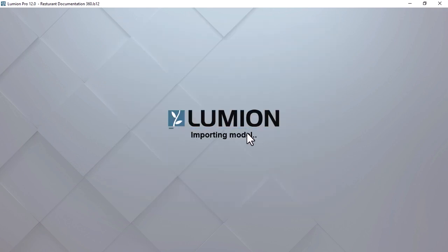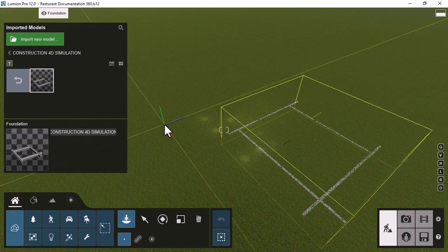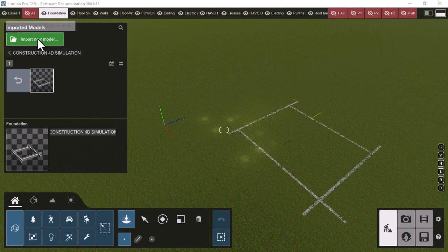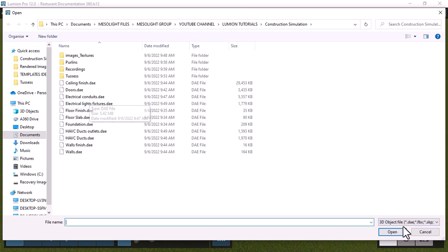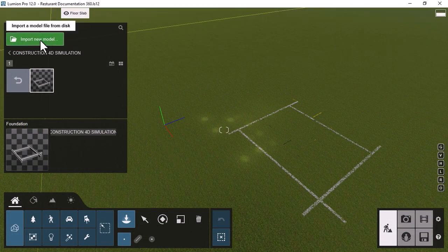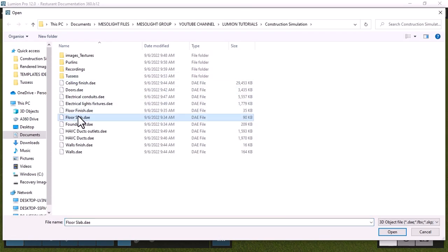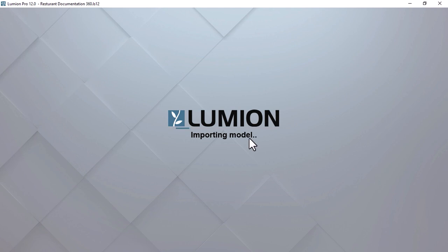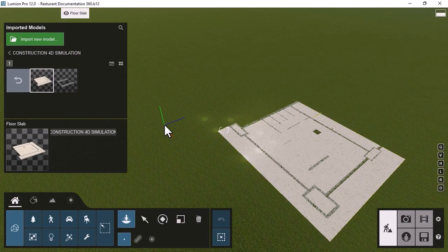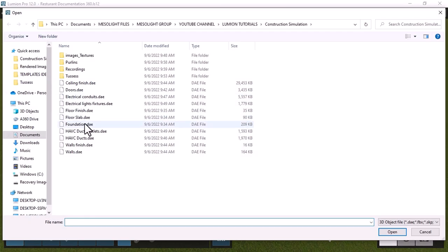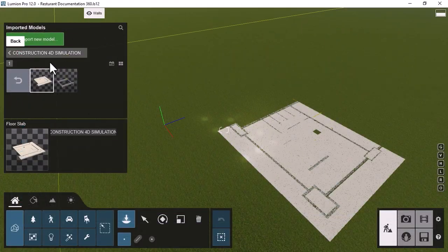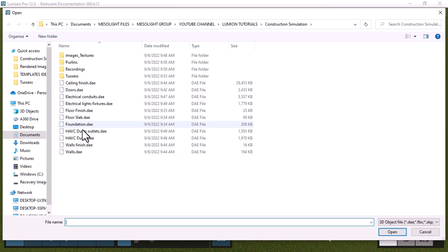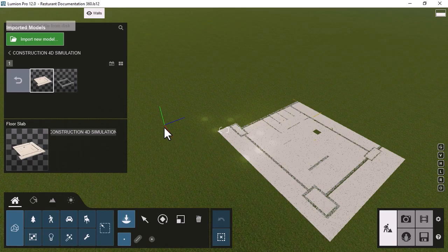When you are importing elements in Lumion and placing them, they have to share the same origin point. It's not a big issue now because we can later use the alignment tool to align all elements. But you would want them to be at least relatively on the origin point, even though it's not accurate, for easy selection when you are trying to align them.